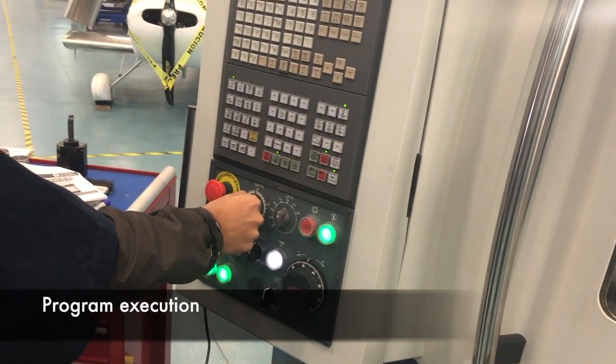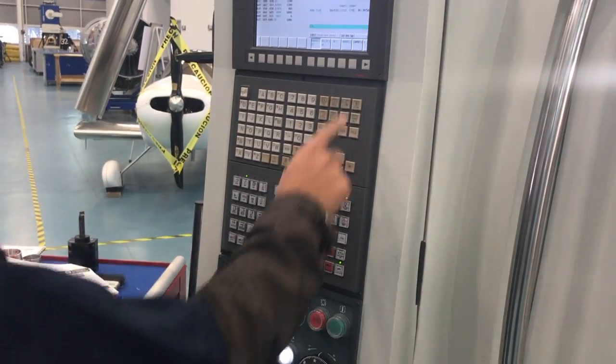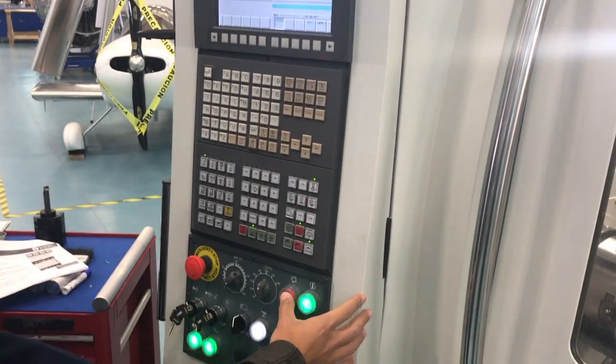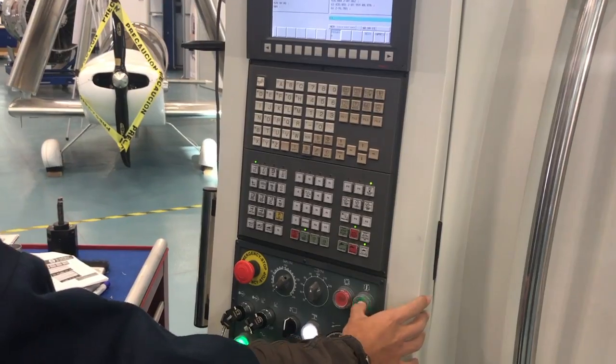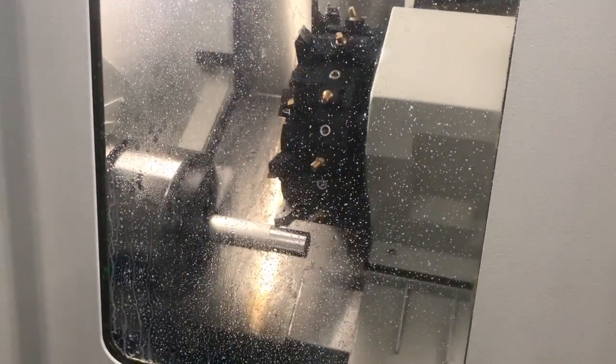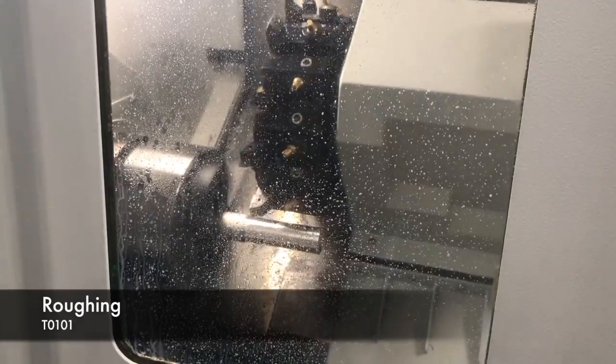We push reset, then position, we lower the speed of the turret, and we start running it in the option auto and pushing the green button. The lathe begins calling the T0101 insert tool, triangle shape, and it uses the same insert tool for the facing process as for the roughing process.